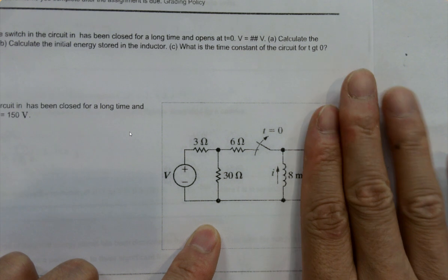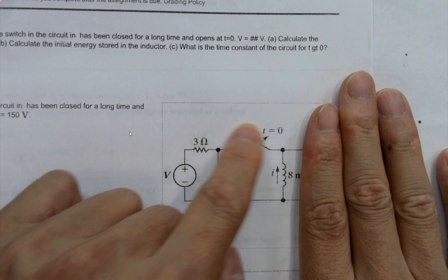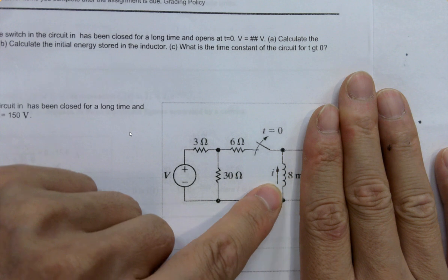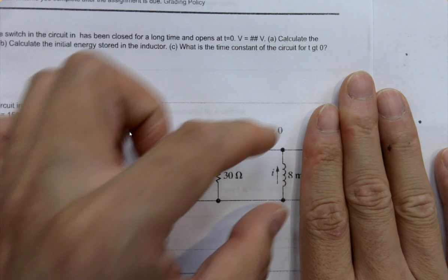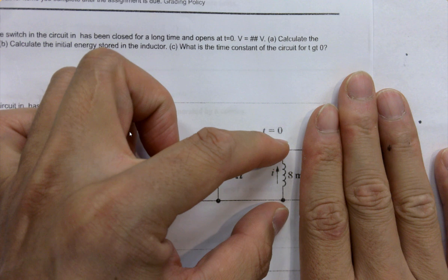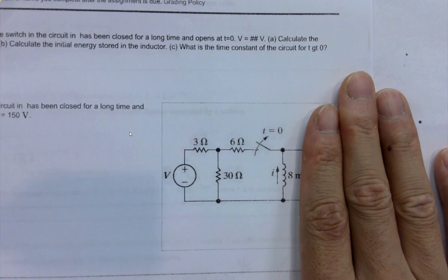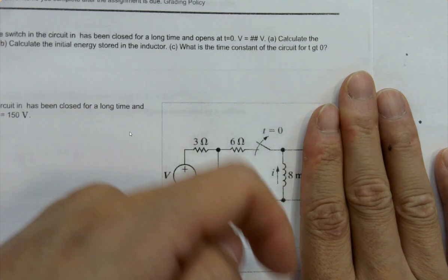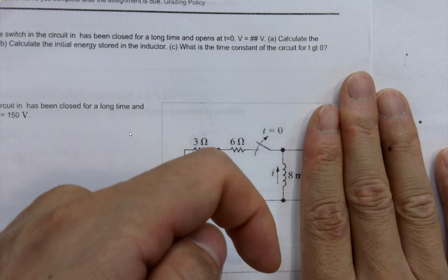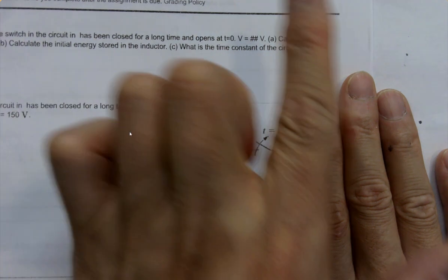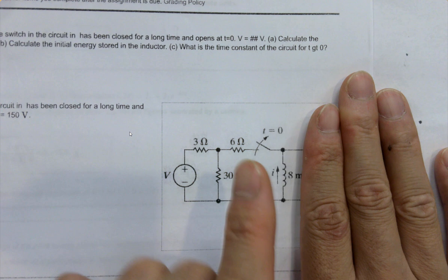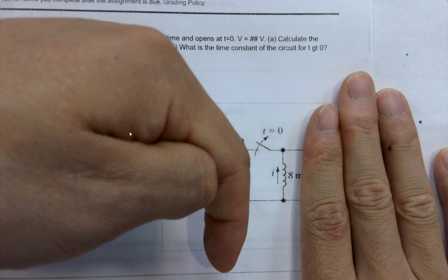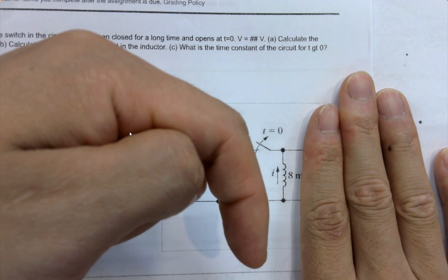This guy got shorted, so this is gone. So you basically have a very simple resistor network like this. Are you able to find the current in here? Yes. Are you able to find the voltage across it? You don't even need to calculate it. Zero. Okay? Make sense? So we've got current stored in the inductor. It's flowing that way, even though the current is labeled that way. However, you know that it's trying to trick you, right? You know it's not true. It's actually that way. You just add a negative sign over it.